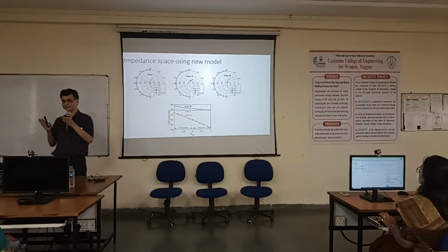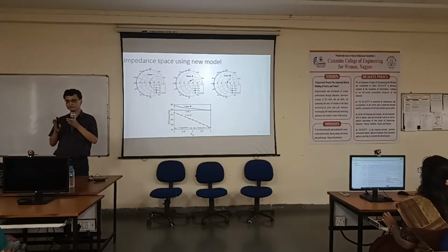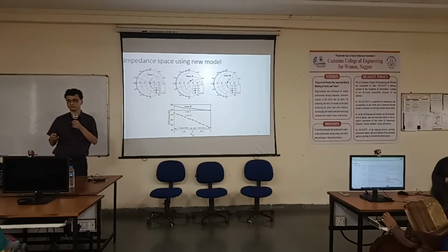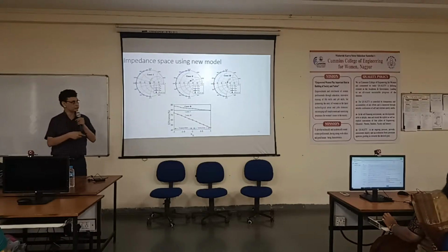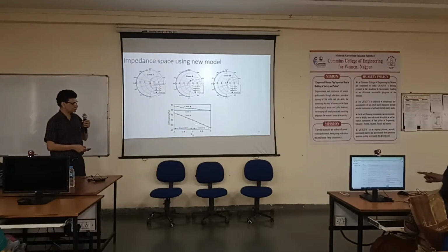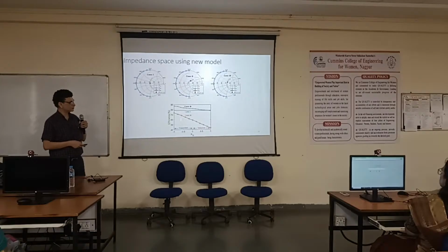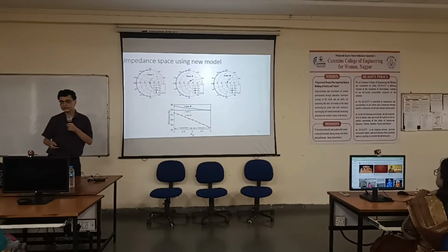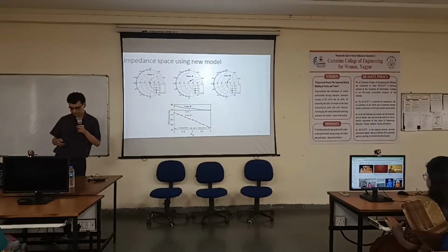If we have a capacitor and an inductor, if both have the same magnitude of reactances, then they should give the opposite effect. But that was not what was being observed, and this was unexplained so far. Using the model and the formulae that we developed, we could explain this case, that for a capacitive load we have higher efficiency. So that is the main conclusion of this work.